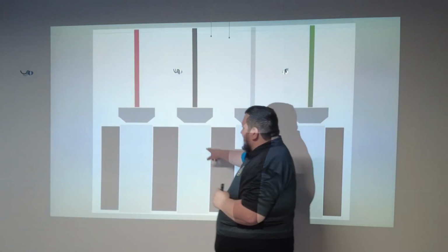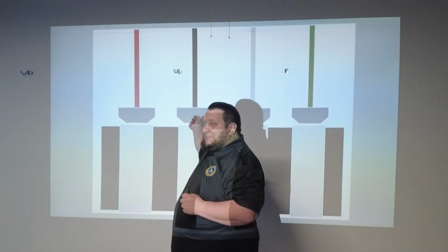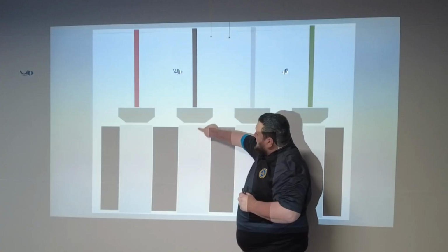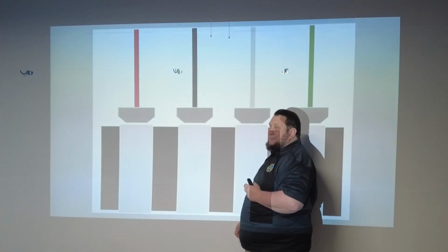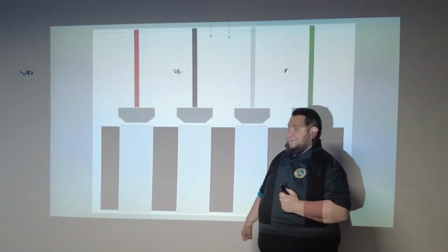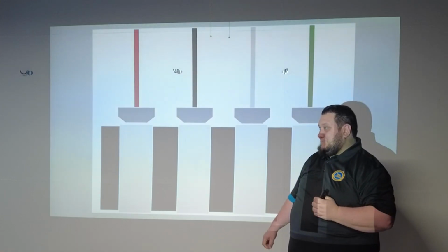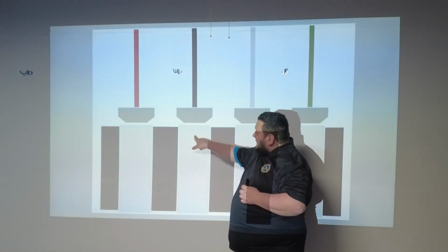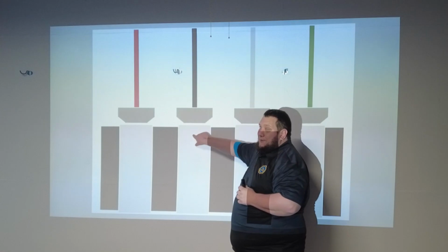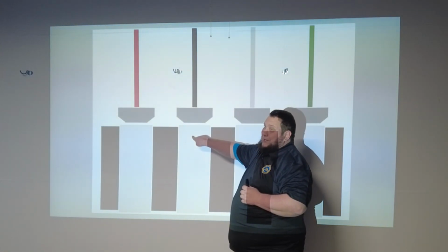Let's say I do the same thing, but my shore breaker is on, I've got power flowing through that cord, and now my dust bunny gets up here and gets trapped. What happens? A spark. A little arc can happen. That little arc creates then a hot spot on the metal that's not going to transfer power.